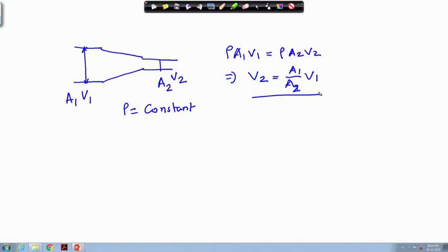We all understand that this is due to the so called spatial component of acceleration, which is very, very important for fluid dynamics, and which is essentially the whole crux of convection based transport processes. So, I think it is important that at this point of time you introduce the concept of substantial derivative or the so called operator D/Dt.